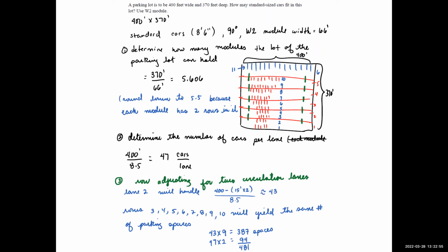Your design again might not be the same, right? In this case, for this design, I used the 400 as the space for locating the perpendicular parking spaces, but you can use that 370 to do the opposite. At the end, I will know whether or not you have the right number of spaces based on the strategy that you decide to follow.